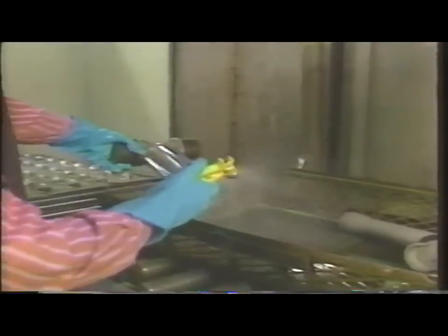This identifies any faults that might be present on the surface, and as shown by the quantity of dye remaining, will indicate the severity of the fault. The dye penetrant used in this technique must be completely removed, because if any is left behind, it will corrode the metal.